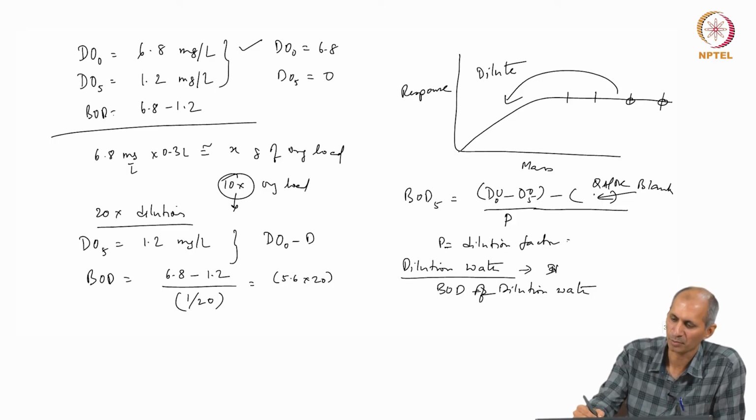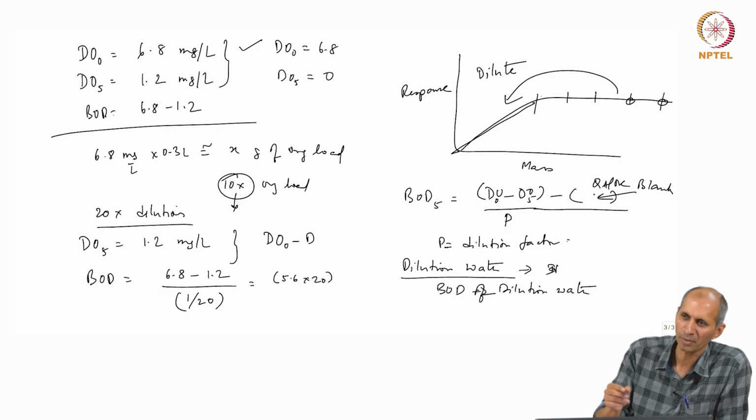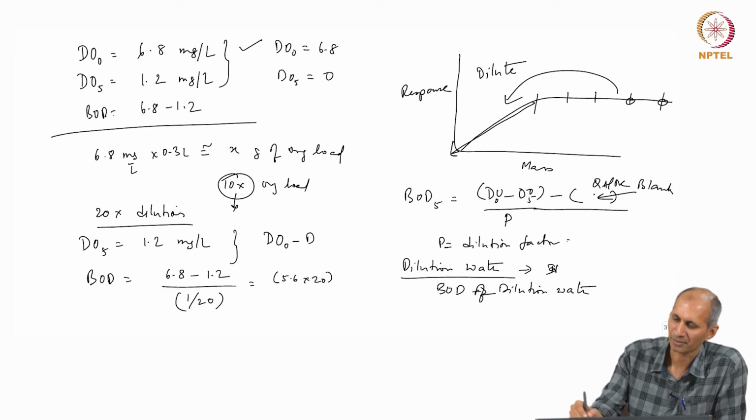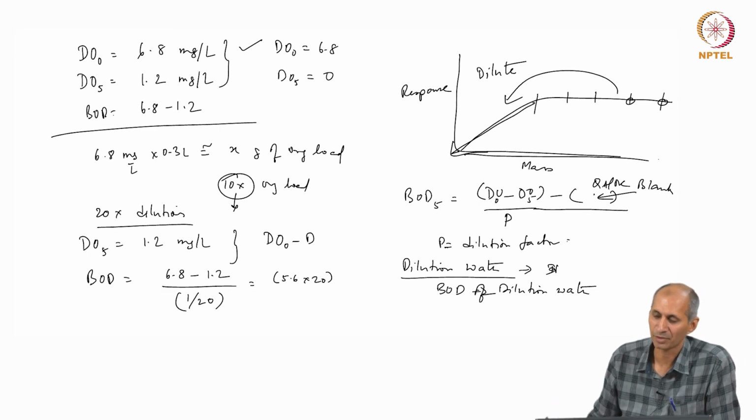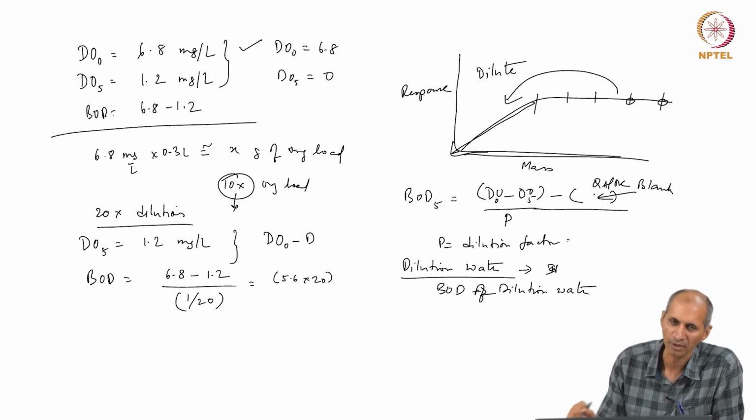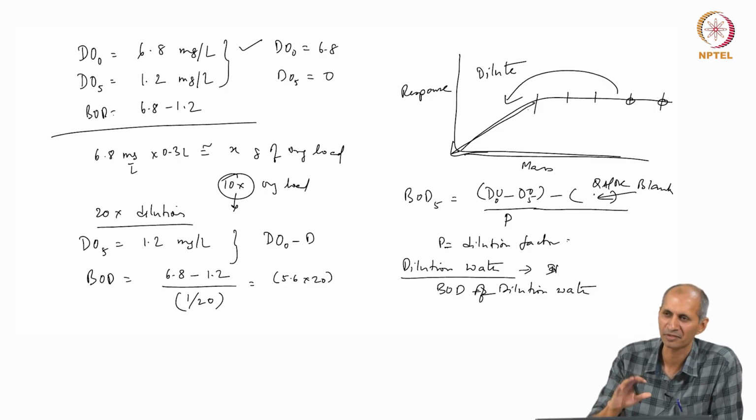Your dissolved oxygen probe is measuring oxygen from one point to another. Which means you have to make standards at multiple concentrations of oxygen, which is very, very difficult to do. So, what people do is they take the maximum concentration of oxygen in water, which is the solubility, saturation.